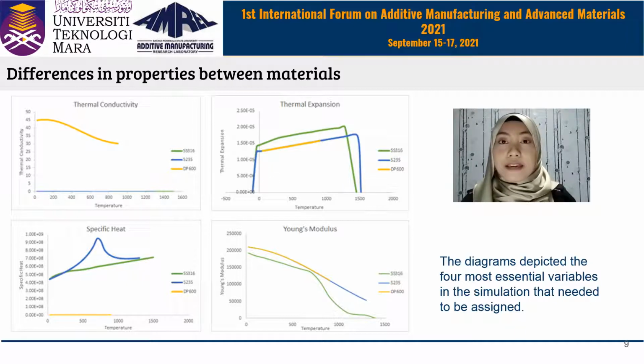For example, if we did not apply thermal conductivity when developing the model, there would most likely be nothing between the body and the plate, because thermal conductivity is one of the main factors in resistance spot welding. If there is no thermal conductivity present, heating definitely will not occur, right?